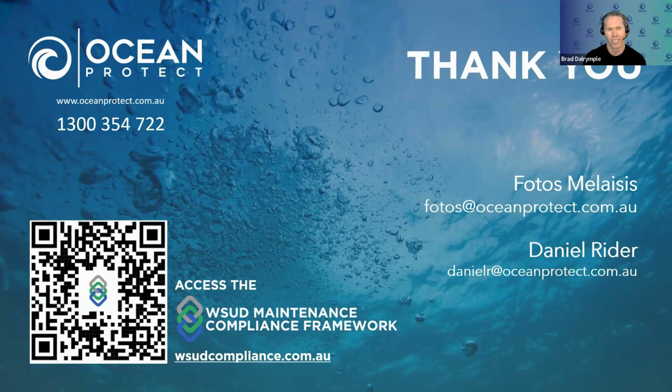Yeah, look, they do something, but it's far easier to stop pollution from entering the waterway before you actually try and capture it after it's already in the waterway. So we can use passively just flowing stormwater to intercept that pollution before it gets downstream into the waterway. Once it's in the waterway, it's far more difficult to remove. And if it's a floating GPT asset, like you see in, say, the Yarra River in Melbourne, that's only capturing the floating plastic. And that's only a very small proportion of the overall plastic load on that waterway. Most plastic sinks, okay?